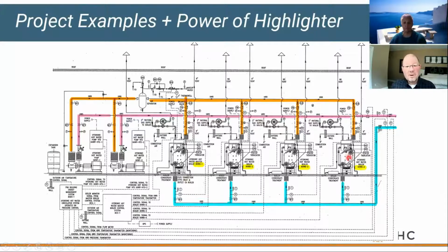If the boilers are firing, I always assume all boilers are firing. We leave the boiler warmer. In this case, I went orange for warm water, and we flow this direction. We go through an air separator and head to our pump suctions, our suction diffusers in this case. Our pumps are putting out higher pressure, so I changed colors to pink, and we're sending warm water under higher pressure out to the system.